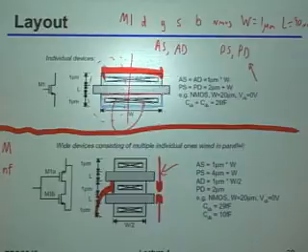By the way, how many of you have ever actually seen this in a Cadence installation before? Okay, great. So maybe we'll do this as a poll. Who thinks they actually understand what the difference between NF and M really is? Okay, what do you think it is? M is just that if you increase it, you just get multiple copies of the same thing, and with NF you increase the number of fingers. So you add more gates to the structure you already have.